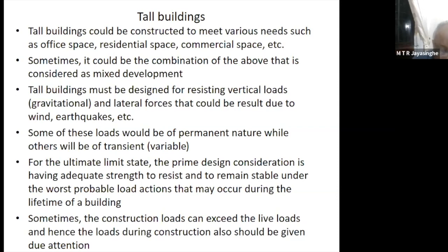And because of arching action, the slabs will be a little stronger than what you actually anticipate. Because of that, it's very hard for a slab to fail, provided that you have compacted the concrete well, cured the concrete well, and used reasonably good quality concrete, especially concrete containing at least 10 to 15% fly ash.